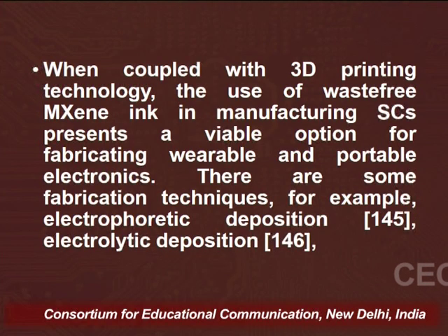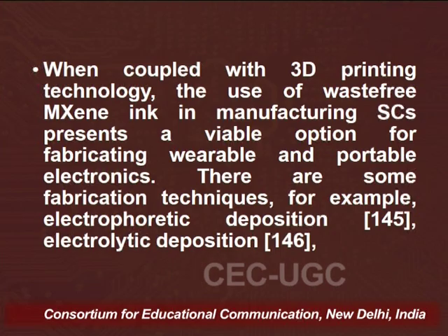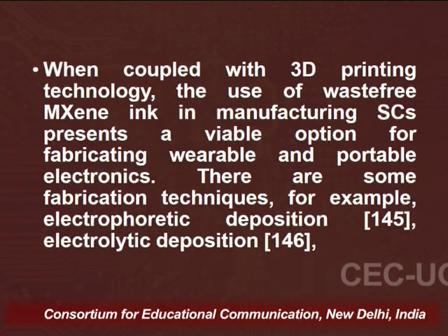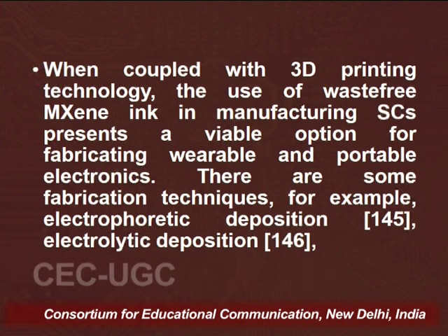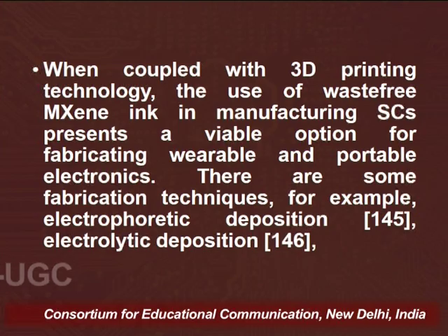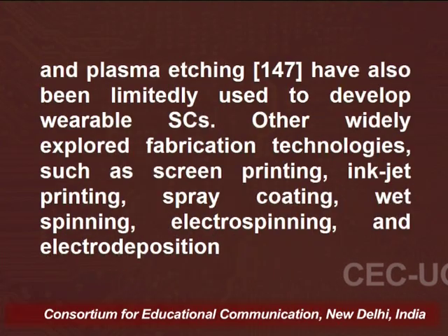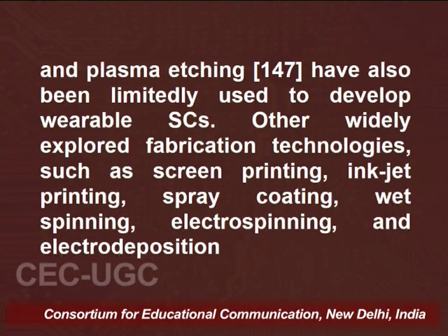So, when coupled with 3D printing technology, the use of waste-free MXene ink in manufacturing supercapacitors presents a viable option for fabricating wearable and portable electronics, and those electronics can be used in sensors as well as in energy storage devices. So, there are some fabrication techniques like electrophoretic deposition, electrolyte deposition and plasma etching, which have limited use for the development of wearable supercapacitors.